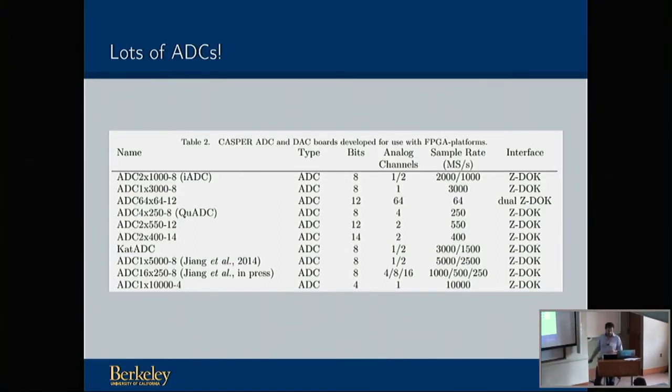All of these ADCs, because this is what we do in CASPER, use the same interface, the idea being that they're all a bit plug and play, chop and change. With one processing board, you can just pick the ADC that matches and plug it in.